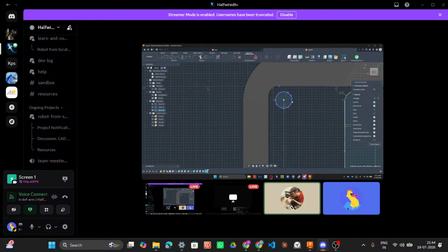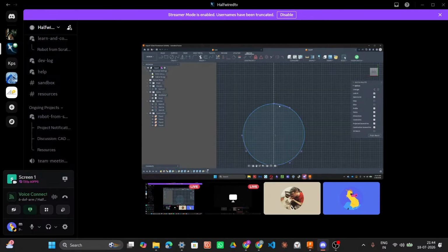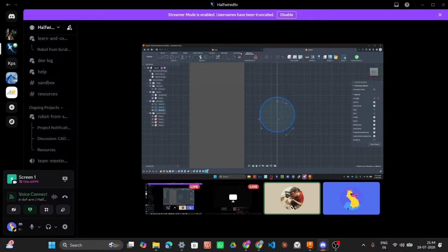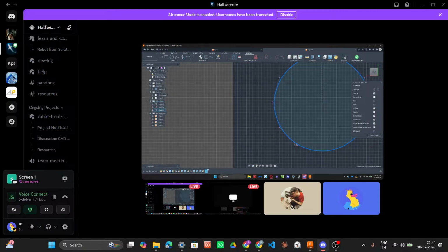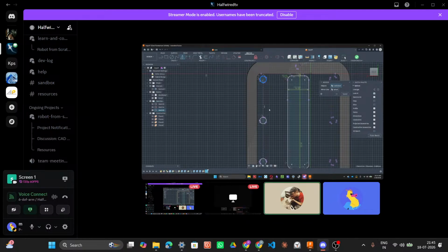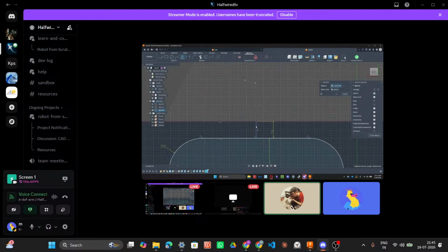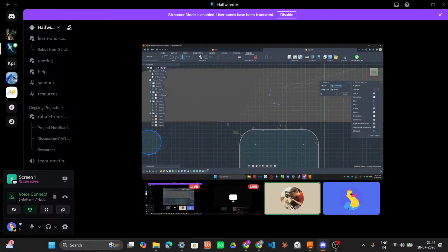Also make them all the same size. And then just to get their placement in this direction, I will make them tangent to just one of these. And then I'll mirror all 3 of them across this line that I already know is centered on my part, oops, I want that as my mirror line.